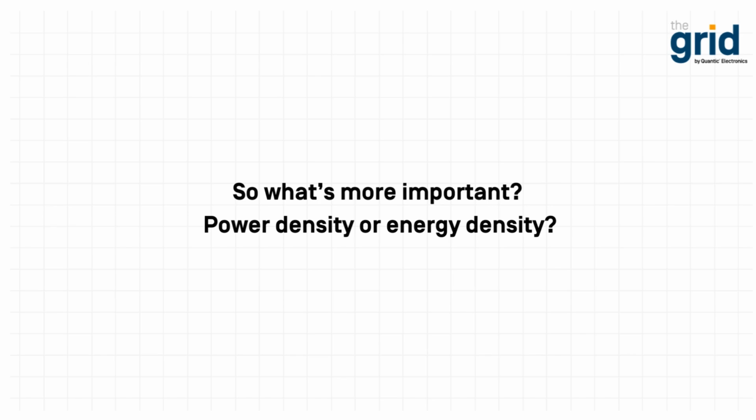Yeah, that's a great question. Now, that actually depends on the application. If your application requires a lot of energy to be stored, but it doesn't require that energy to be accessed quickly, then energy density would be the key parameter. If that energy needs to be accessed rapidly, like a high power pulse laser, then power density becomes far more important. Understanding both attributes helps to truly compare the capacitor options to ensure the most efficient option is chosen. But really, again, it's truly dependent on that application, the power needs of the application there. But again, a great question.